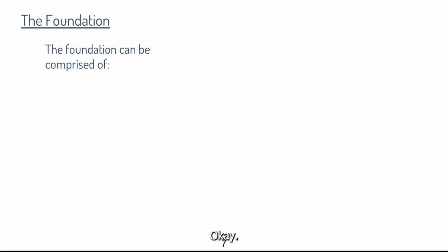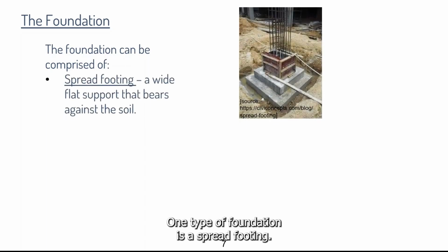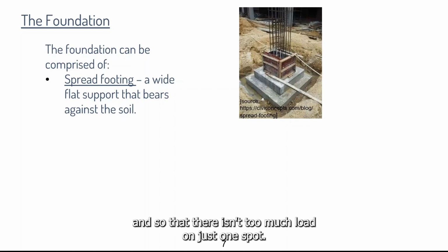Anyways, foundations support the bridge. They take the load path into the soil or the earth. One type of foundation is a spread footing. This is a wide, flat foot that spreads out the load so that the soil can carry it and so that there isn't too much load on just one spot.